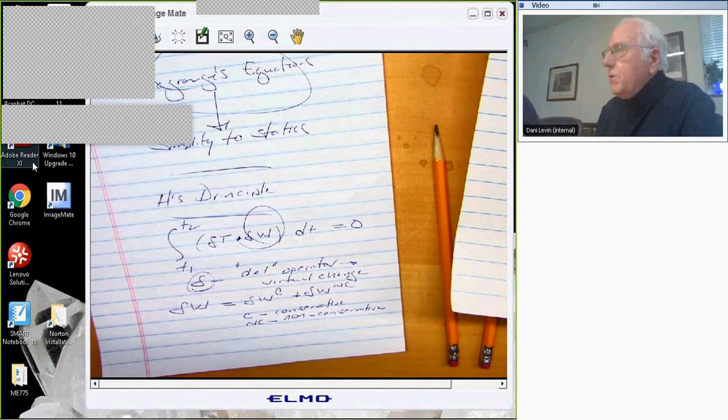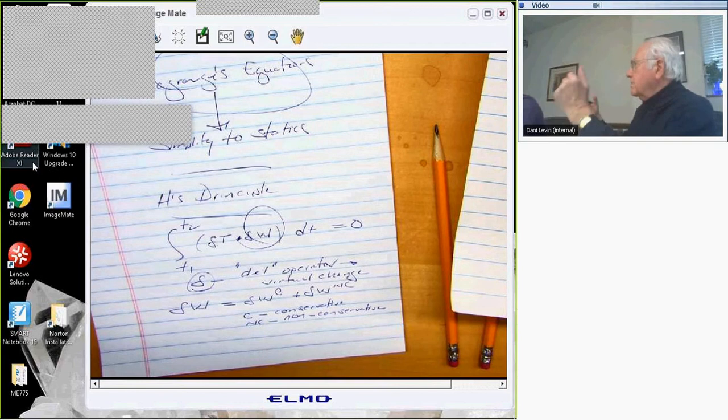The exception to that, of course, is damping in structures, right? And so we have to account for the damping of the structure, and we'll talk about that later on, but basically we make it up. It's the Achilles heel of structural dynamic analysis. We go to all this effort to get kinetic energy and potential energy and go to a great effort to describe those quantities and their implications. And then right at the end, we just sort of throw in a term which, oh, we need some damping.